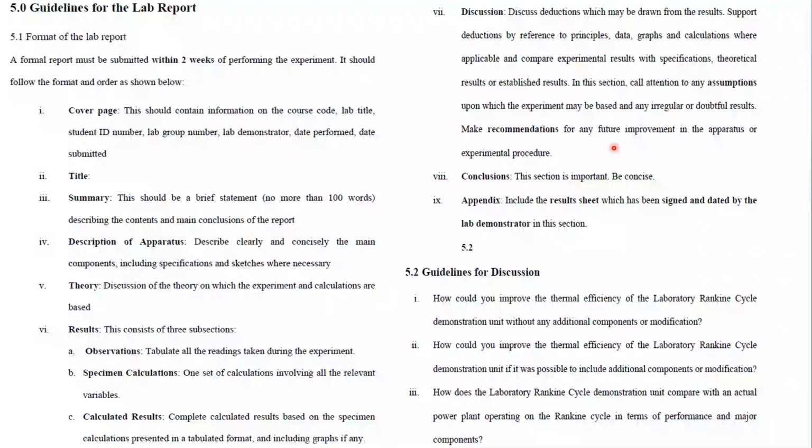And also, although the steam at the turbine inlet is superheated, as we throttle the steam from the boiler outlet from 1 to 2, it becomes superheated to enter the turbine. Even though this steam is superheated, the apparatus is fairly old, really old. Over time, as steam continuously passes through the turbine blades, we tend to have condensation on the blades of the turbine.